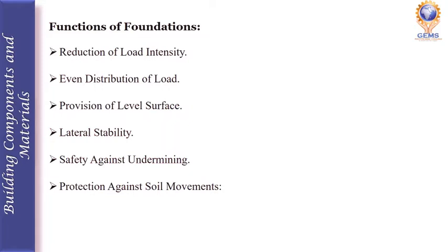And the second one is even distribution of load. So the foundation can distribute the non-uniform load of the superstructure evenly to the subsoil. So not an uneven distribution, it can evenly distribute the load to the subsoil.